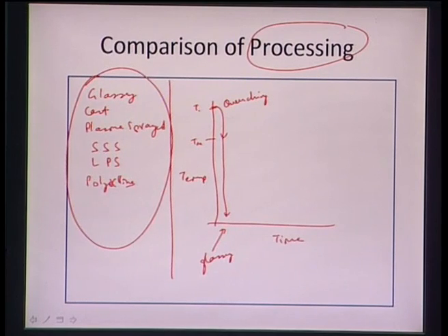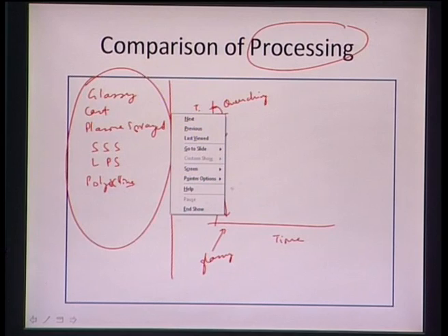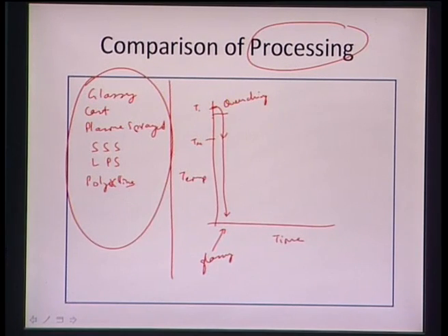For the cast structure, we also take it to very high temperatures, put it in a mold and then let it cool in the mold. That comes eventually via homogenization. So we take it to high temperatures, let it homogenize for some time, and then cool it down to room temperature. In this case of casting we can also get some sort of microstructure. But the problem with casting is we can get very coarse grains, and once we have very coarse grains we can also get deterioration in all the mechanical properties. We can also see sometimes shrinkage cavities, which will again deteriorate the properties of the material and lead to environmental degradation.